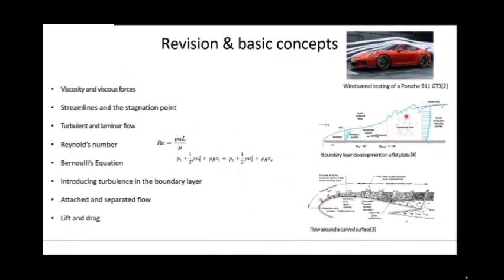And if we're increasing the kinetic energy in our boundary layer by drawing down kinetic energy from outside of our boundary layer, we will encourage that velocity to remain positive, and therefore we would see attached flow later on because we've increased the kinetic energy in our boundary layer.